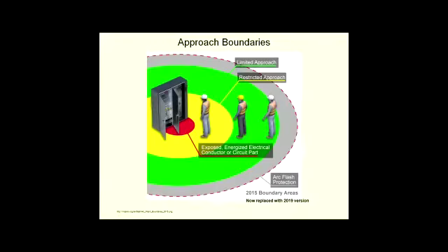So when it comes to arc flash or electrical equipment that can cause arc flash, we do have boundaries. If somebody asks me what the distance is between the boundaries, it basically determines how close you can stand to the electrical equipment before, if an arc flash happens, you're put in a certain level of danger.